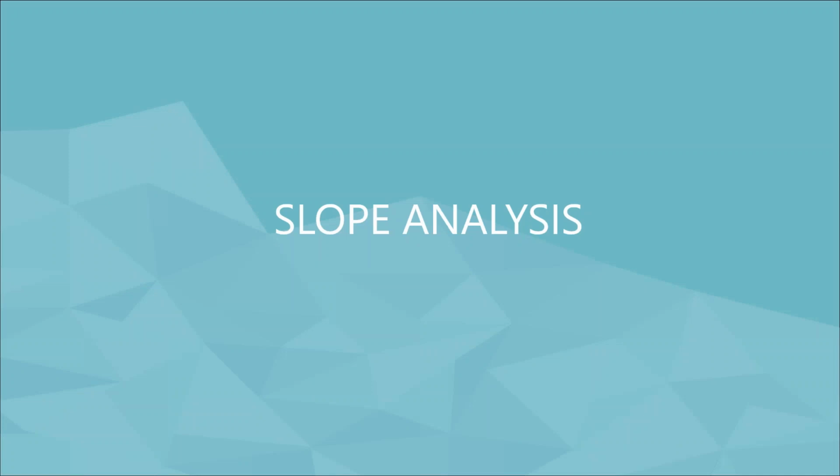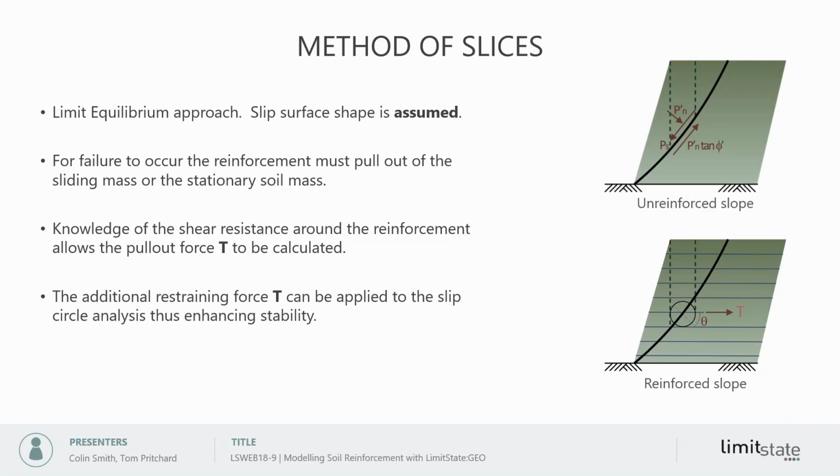Now, in terms of analysis, if we look at a classical approach to slope analysis with reinforcing elements, typically it's a limit equilibrium approach. You might use the method of slices. So you pre-assume a slip surface, and you can look at the equilibrium of forces along that slip surface in terms of shear and normal force and available resistance.